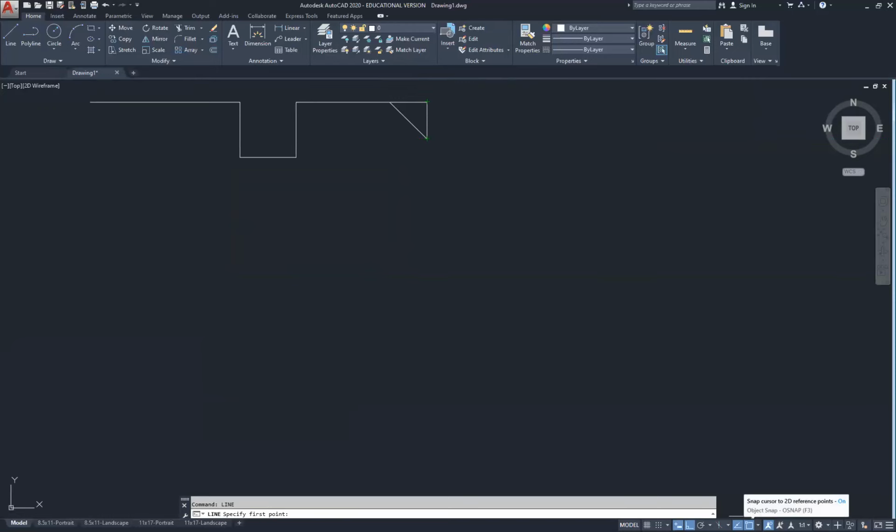That distance of 2 that we didn't use earlier is dimensioning that line at the bottom. So we'll dimension that at 2. Then we're going to go down the difference from 3.5 to 2.5, which is 1. Then come back forward 2, or to the left.